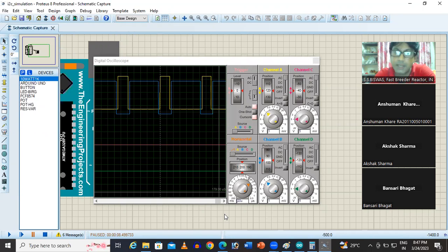Otherwise, every time the AND gate output will be 0. But once this AND gate output is high, that output will be taken to the external hardware interrupt pin of the microcontroller. And once this rising edge has occurred, immediately you should turn off the timer. Turning off the timer means you make the clock bits 000. Again, you need to reset. So your switch will not be damaged.